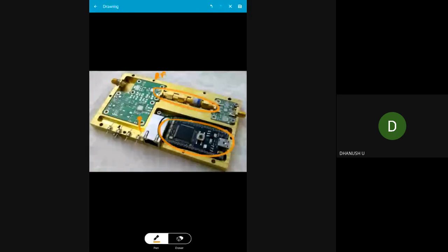All these now, presently, we are using microstrip. Even though it is leaky, we are able to minimize that effect using simulation CAD tools. We are trying to minimize the thickness of the substrate, and by choosing the right dielectric medium. That is why we are moving around microstrips, and that is the reason it is more popular than strip lines.